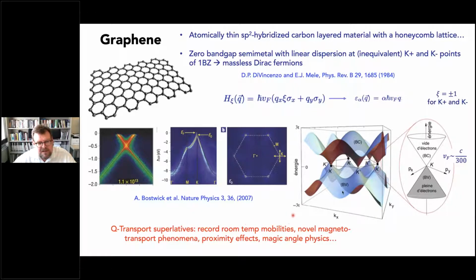But for me, as a guy who does optics and has done optics for a long time, graphene's a bit of a letdown because it doesn't have a band gap. And that also means that it's difficult to make devices like transistors, semiconductor devices, where you want to use electric fields, metal gates to control the electron density. So in a way, you can shift the Fermi level around, you can change the electron density and the hole density, but you would like to have other materials.